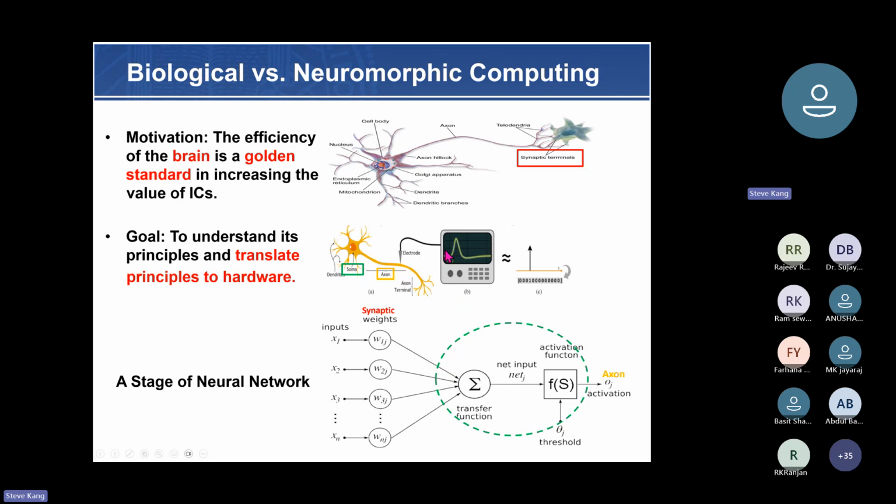So this is the action potential, the neuronal pulse signal, which can be approximated by a pulse like here, digitally speaking, right? And so there can be many inputs coming in with different weights and summed, and then go through a thresholding operation, a comparator circuit, whether it exceeds a certain value or not. If it's exceeding a certain value, you have a firing here. If it's below that, it dies, for instance.